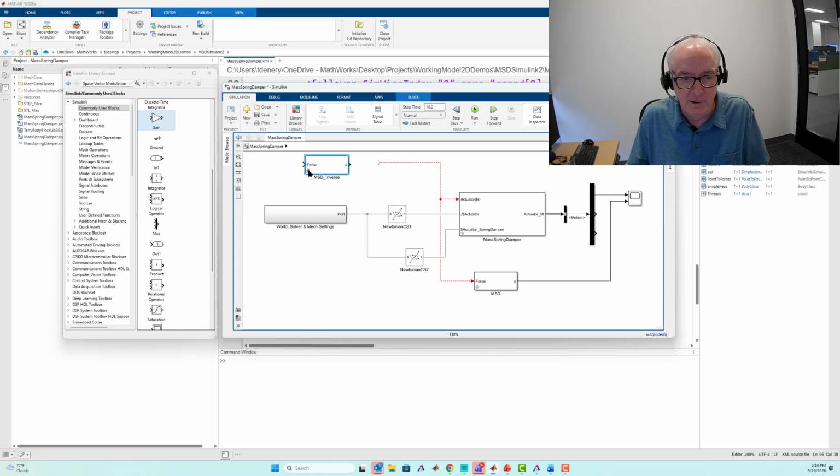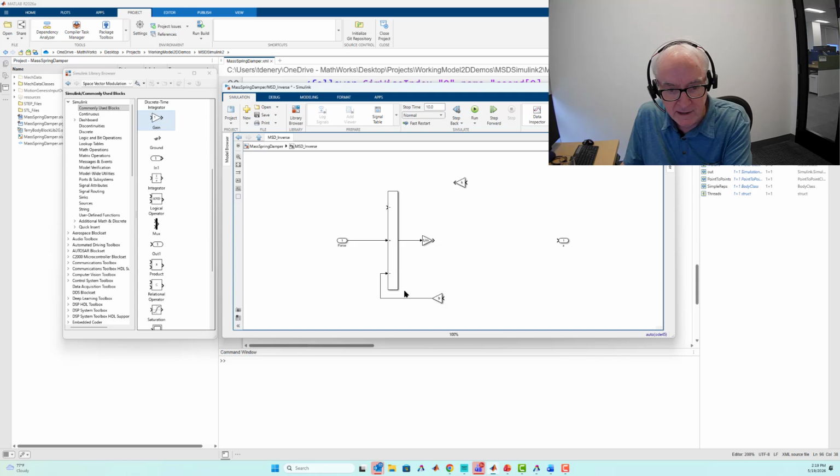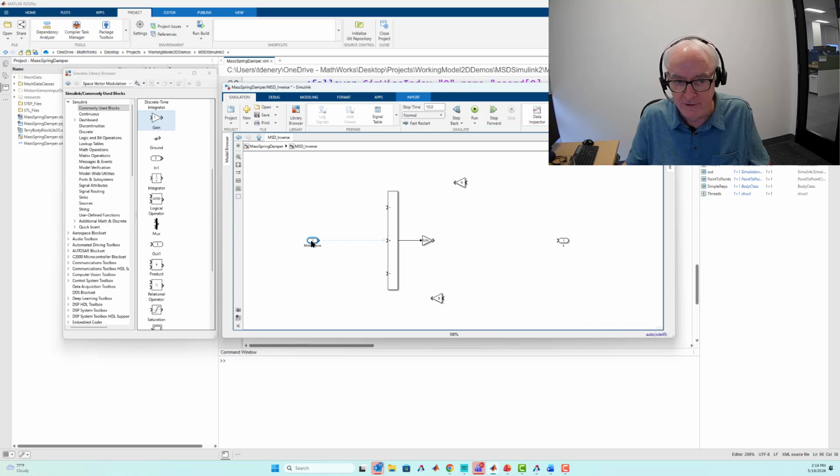All right, so we'll get there in a moment, but let me get started by going back in here. First of all, we're not going to do calculus anymore, so we're going to get rid of these integrators. I like keeping all this stuff, but we have to do some redecorating. It'll begin with my input port. I'm going to name this motion, since it's now our input, with a little designation of PVA, indicating position, velocity, and acceleration.